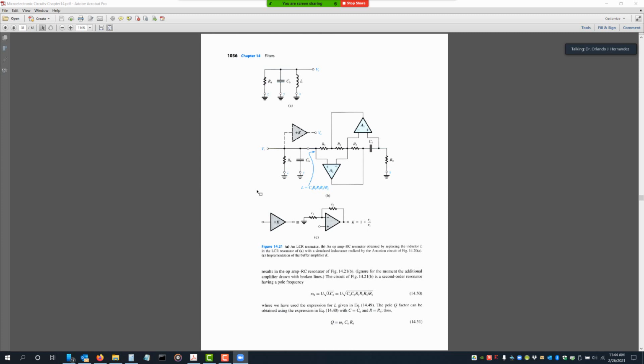The meaningful impedance for an inductor requires either a high inductance, which means large physical size and bulky, or a large frequency, because the impedance of the inductor is S times L, or 2 pi FL, and that's how you can see the dependence on the frequency and the inductance. Did that answer the question? Yeah, it did. Thank you.